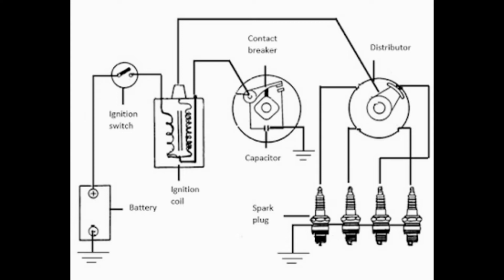4. Ignition coil. It is used to produce high voltage sufficient to generate spark across the electrodes of the spark plug. It acts as a step-up transformer and converts a 6 or 12 V of a battery into a very high voltage of about 15,000 to 30,000 V. It consists of a soft iron core surrounded by two insulated coils, named as primary winding and secondary winding. The primary winding consists of 200-300 turns of 20-gauge wires capable of producing resistance of 1.15 ohm.